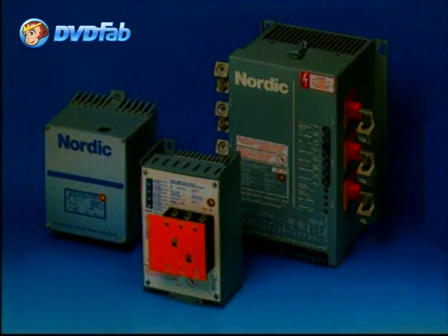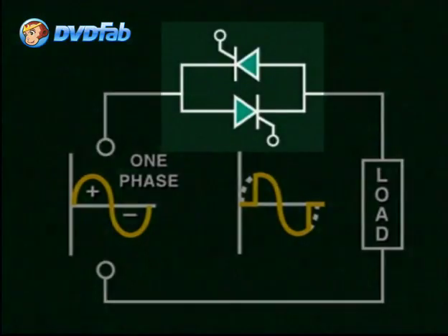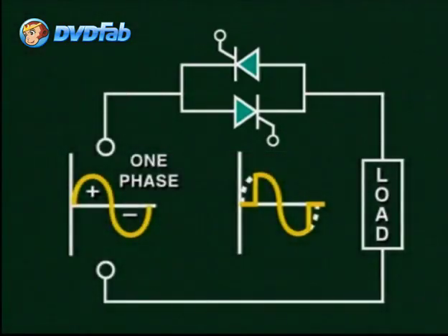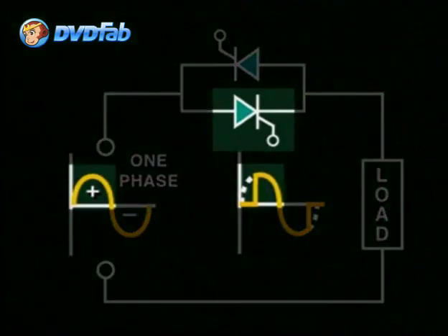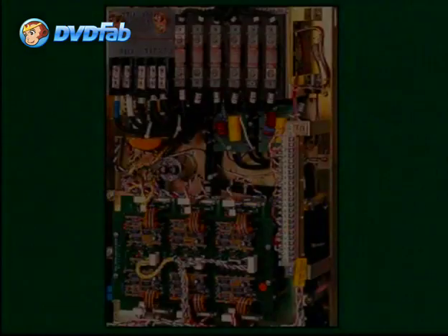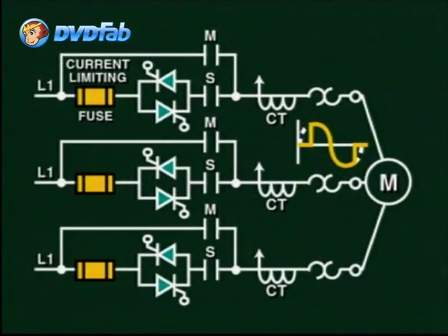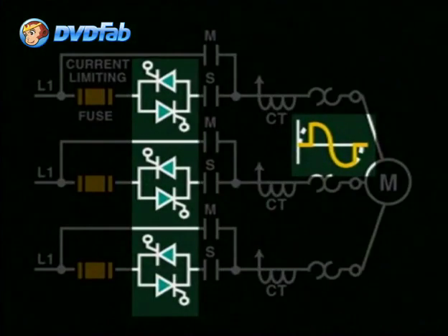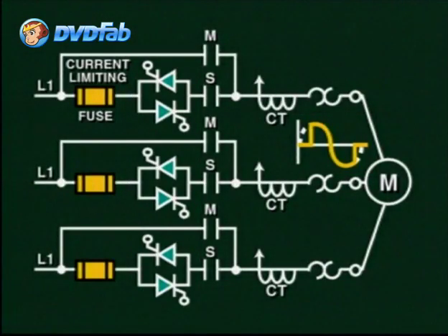Solid-state starters, also called soft starters, employ SCRs to implement the reduced voltage start. In this configuration, two SCRs are paired off to control the AC voltage of each phase. One SCR controls the positive swing of the voltage, while the other controls the negative swing. The control of the SCR's gate is performed by other electronic circuitry in the starter. Essentially, the SCR's gate is controlled to let through part of the AC voltage. In this manner, the motor will see reduced voltage current.